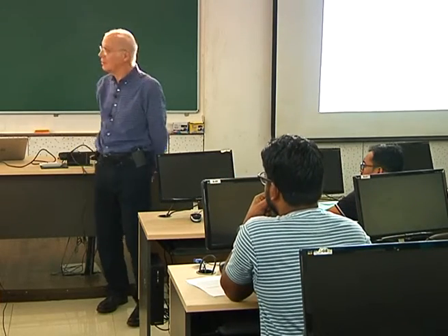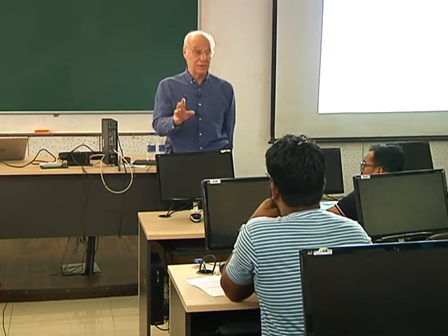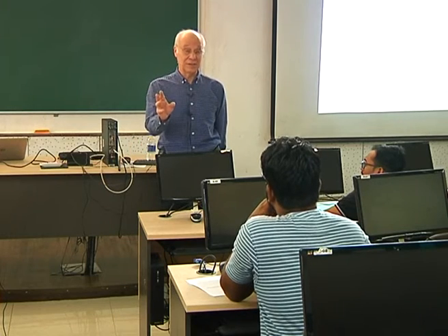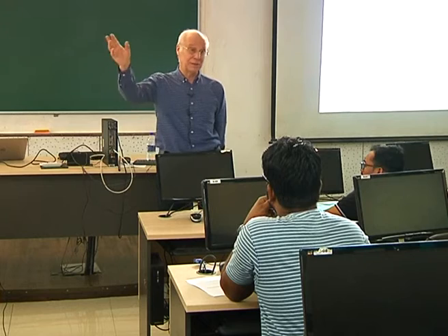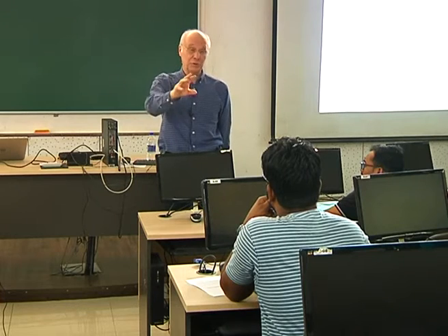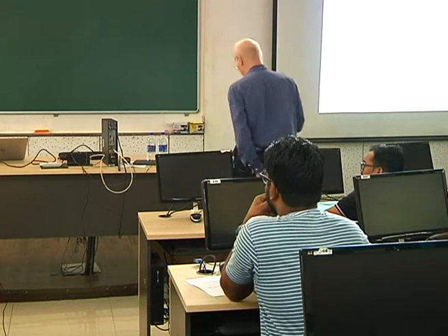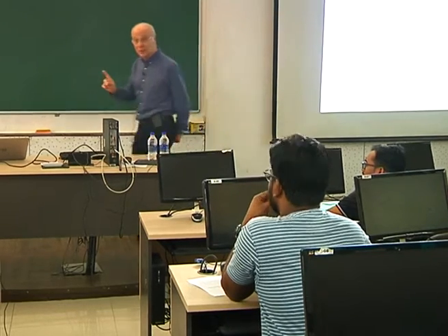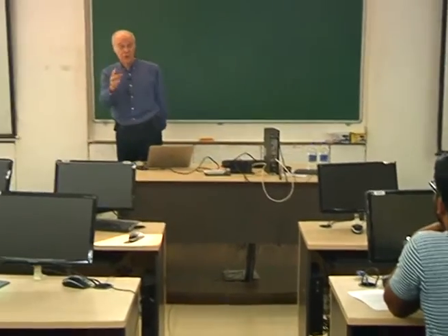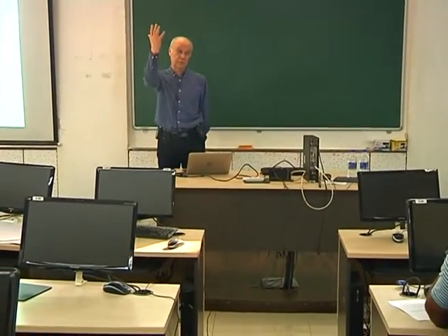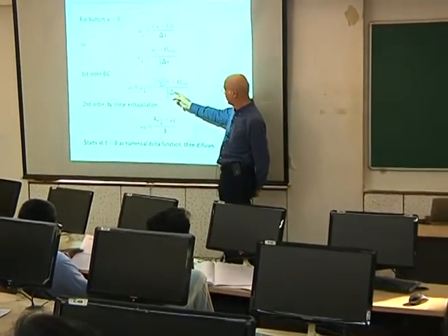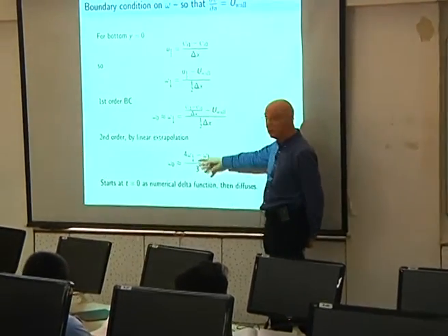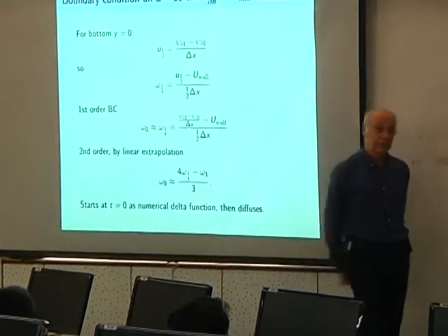Yeah, you could. Okay. So one way of finding out what the errors are is to do a Taylor series expansion, include lots of extra terms, and it will tell you what the errors are. So you should find that the vorticity on the wall, if you do a Taylor series expansion of the stream function away from the wall, will end up being the first order term is this, and this is a second order delta x squared error term.